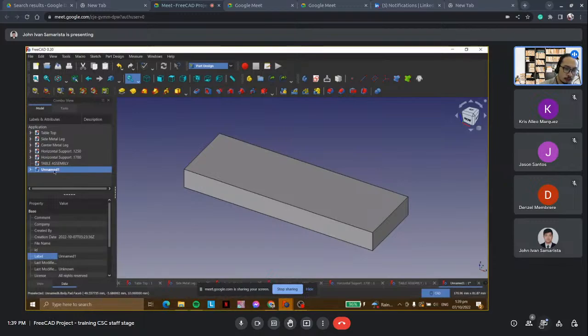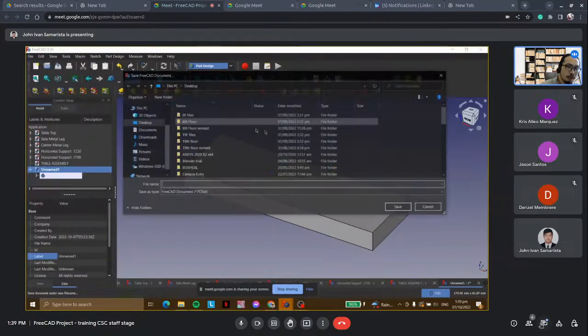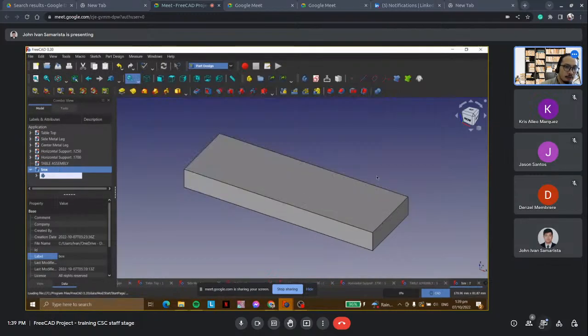So typically you use Sketcher, which is a 2D drawing tool, and then after that you use Part Design to give it 3 dimensions. And yeah, each one of these are different files. Okay.